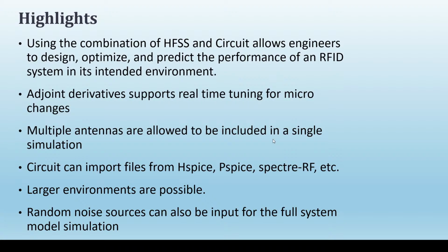We also allow you to model multiple antennas in a single simulation. So in a single environment, you can do a multiple antenna design in one simulation and plot different results. Again, if you don't want to create your circuit again, if you designed it in other tools, you can always import the S parameter file, or you can even import files from HSpice, PSpice, Spectre RF, etc.